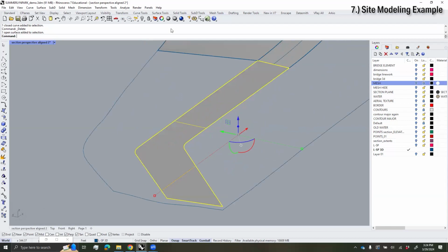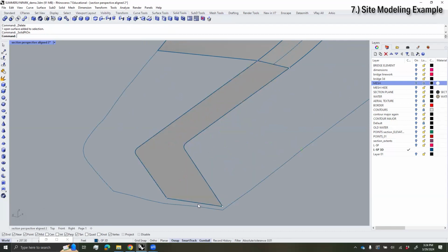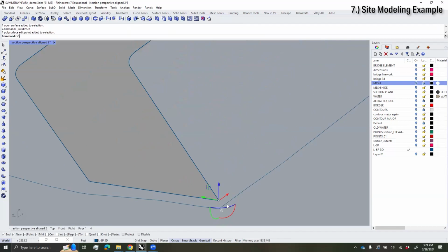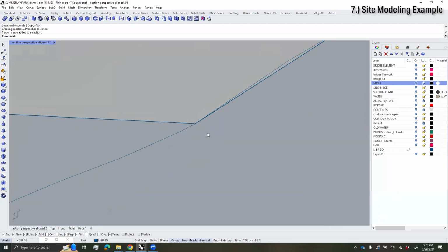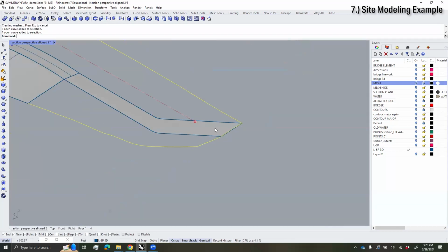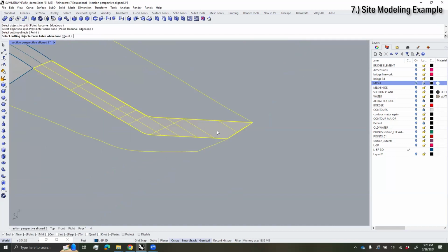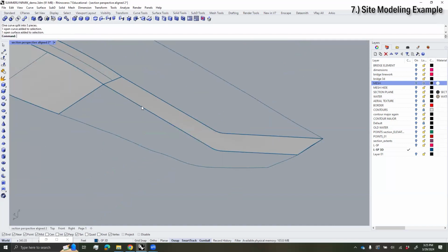Now, if you choose this, you can go to the solid tools tab at the top, and then there is this turn on solid control points. Click on that, you see these little endpoints of the surface there. You can take that now, and you can use set point, and just set it to be at the elevation that meets existing grade. Let's split this curve using this surface here. Let's see if that will work. So split this using this. So we'll now do duplicate edge, edge that, take those two, join those, join to that, and then patch.